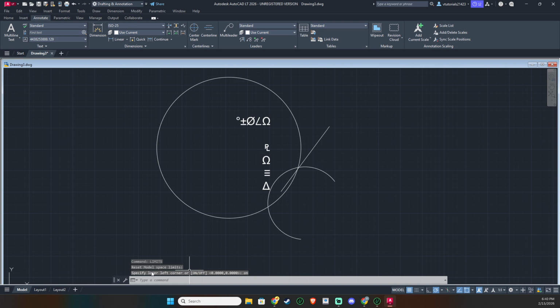This quick check helps you see whether your workspace is too small, too large, or simply not aligned with your needs. If you want to change them, you'll set two corners, just like defining a rectangle. When prompted for the lower left corner, type 0,0 and press enter. That places the origin at the lower left of your working area, which is a common and clean starting point.